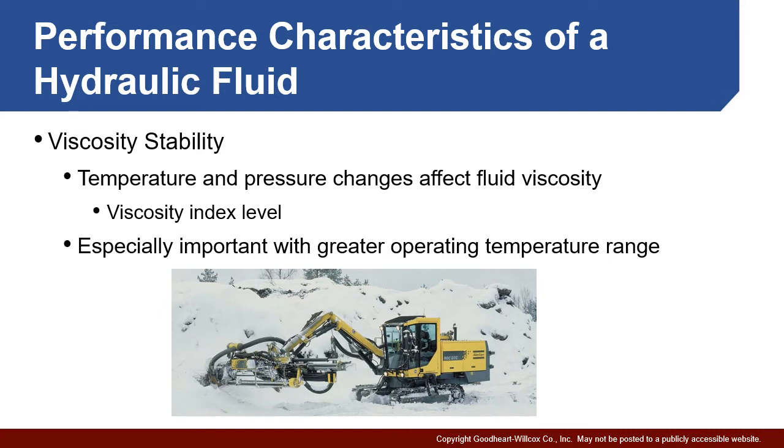But if we're in a situation where we have a wide operating temperature range, for example, below you see a piece of construction equipment used outdoors, potentially in a northern climate, in that case, you may have very low temperatures that you need to maintain the viscosity in, meaning the fluid still has to flow even when it's very cold. There's a number of alternatives, things like oil heaters and stuff like that that can be used, but we want to make sure that given our application that our fluid is going to be functional at both the highest and lowest temperatures that we're going to see.